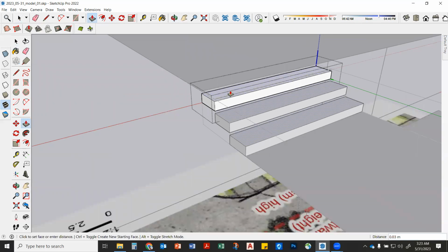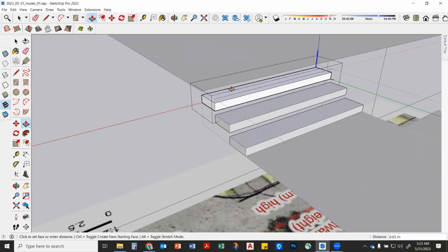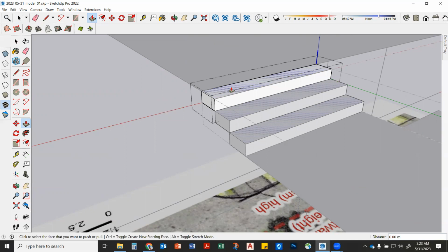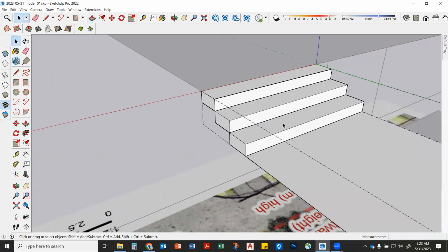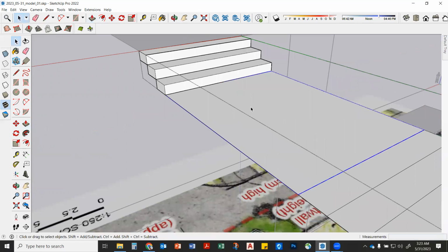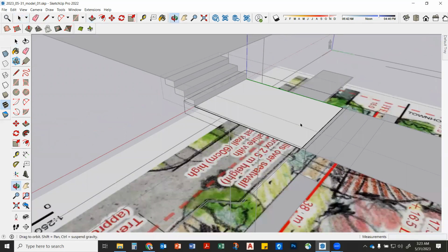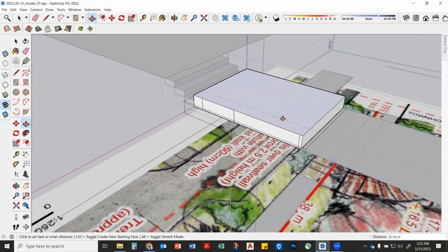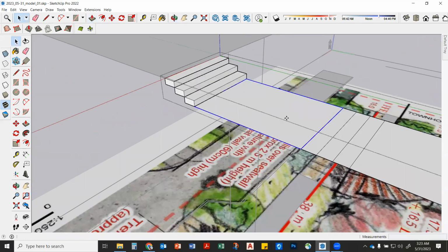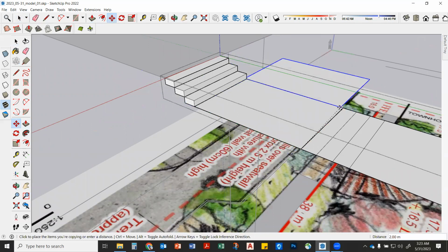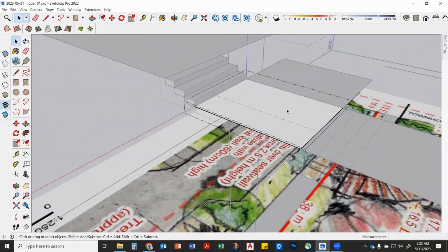And then if I wanted to make them a little bit smaller or a little bit bigger, all of them will change the exact same. Okay, so that's a component, yeah? Versus a group makes it separate, right? Doesn't stick to everything else. But if I change this, there's no copies of it anywhere, right? Even if I take this and I move it and I make a copy like I was doing, right? If I make a copy there, the difference between a group and a component is that group won't copy, right? Won't do the same thing as the component.